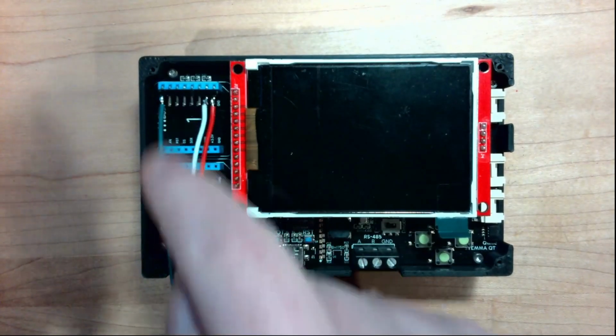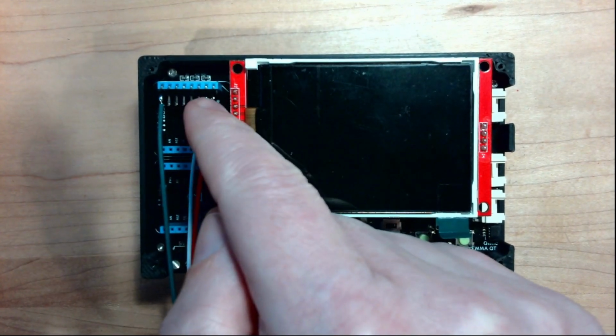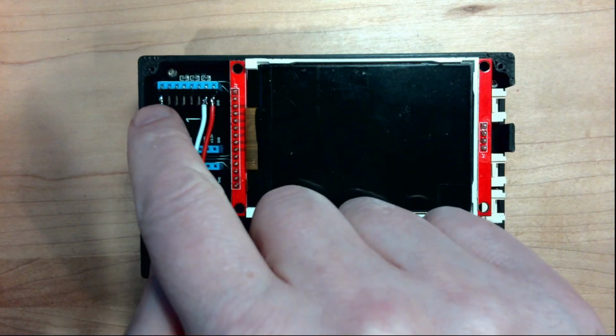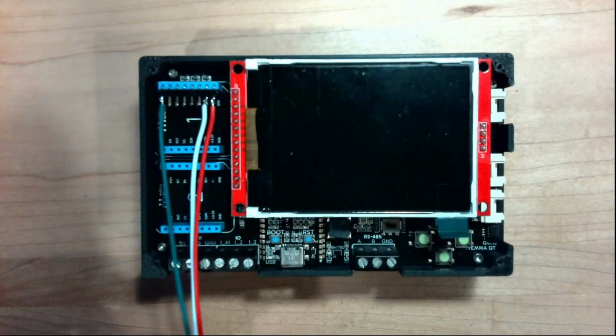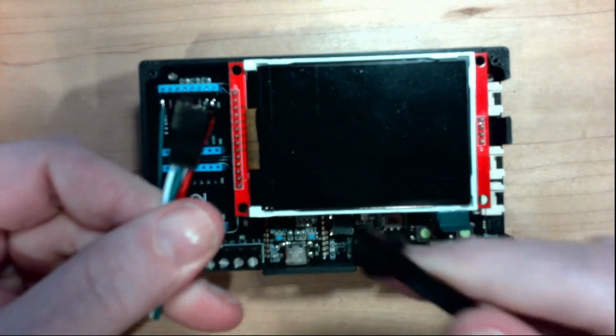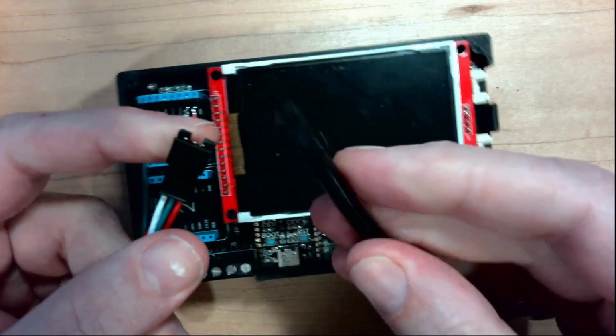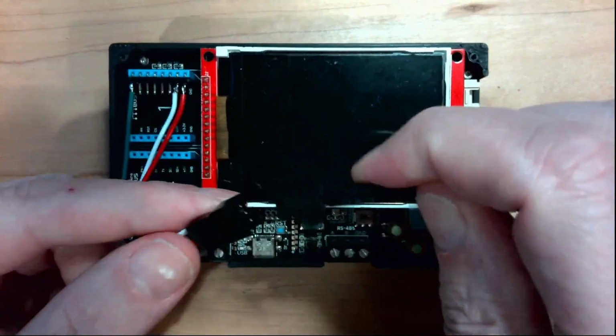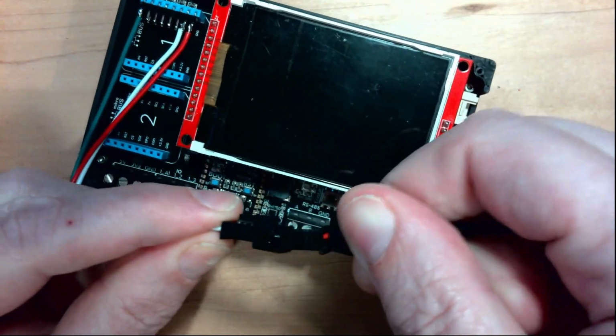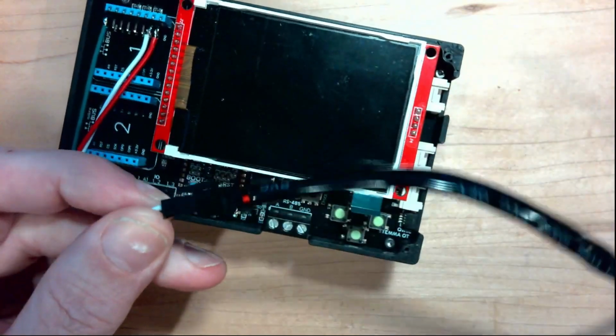This hardware has a microbus connector, so we've got ground and power here. And then for signal, I'm just going in on the PWM signal. And that comes to one of these. And most of these sensors I find have this 3-pin connector on it, so we can just connect them together, and now we're wired up.